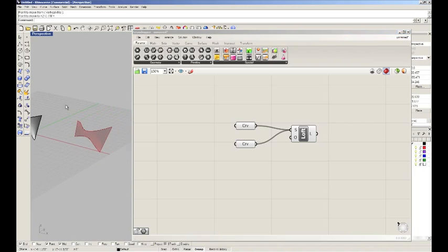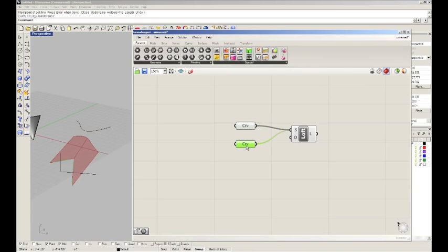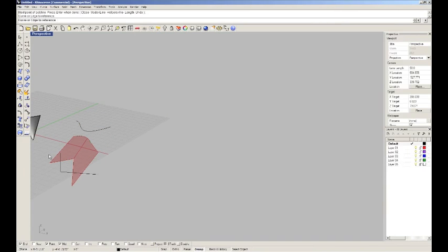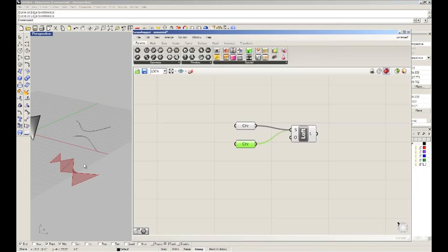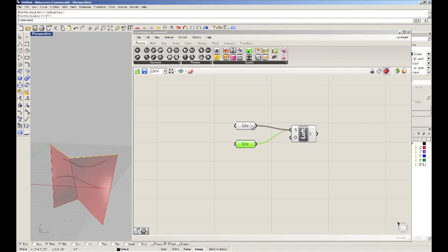So for instance, I can create a much more angular curve out of polylines, and right-click and set one curve, right-click and set one curve, and move one of those curves vertically, and have the same relationship created but between different curves.